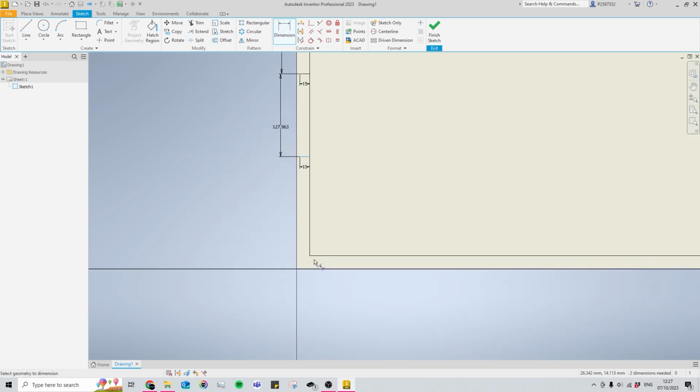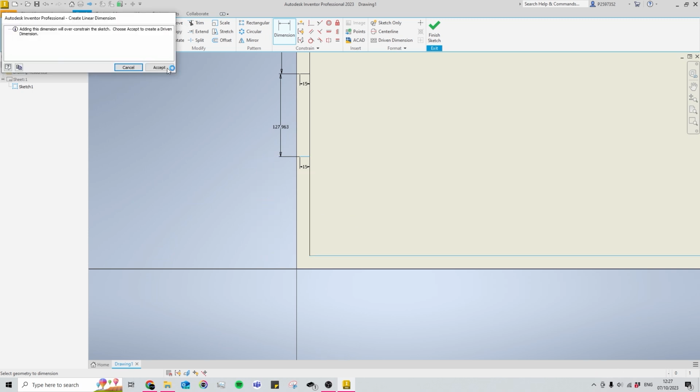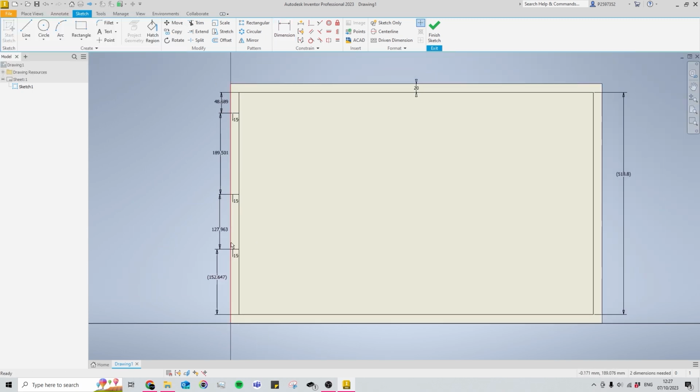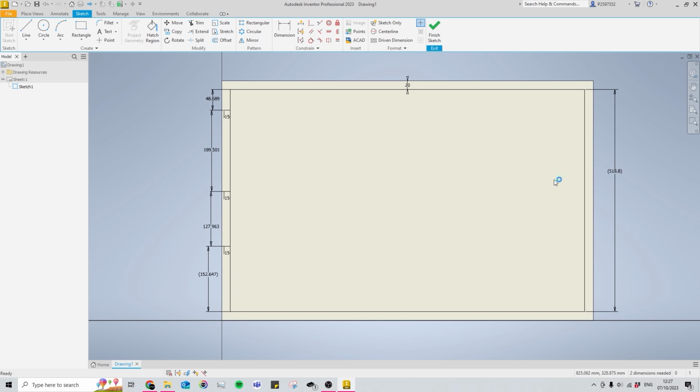And now that all our dimensions are in here, we can start using these to equally space them. So we know that each of these areas needs to be 1/4 of our driven dimension or our overall page space on the right hand side here. So if I click into this dimension and then use this dimension as our starting point and then use divided by 4, you'll see that it is now at that dimension divided by 4.